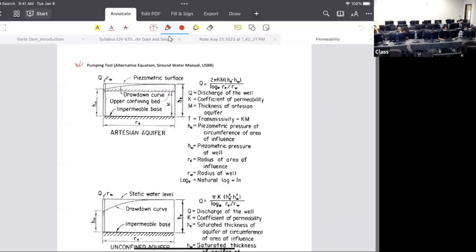Okay. But can we understand the permeability of some soil, not from a direct result, but a passive result from a resistivity test? I mean, can we have some idea about the permeability of some soil using a resistivity test? Yeah, sure, we can. But it is not going to be very accurate. Using resistivity, we won't get the direct results, but we will get indirect results, for sure.